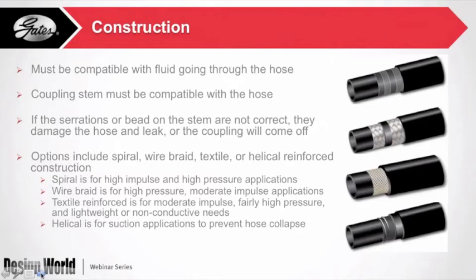Textile reinforced hoses are a little more forgiving. A lot of your textile reinforced hoses are also not the highest pressure. Some of them are going to be around 500 psi or below. So again, this opens up the opportunity for different attachment types. So we can do a push lock fitting for air, water, or multi-purpose hose, that sort of thing, where it won't need to be clamped or crimped. But always make sure that your coupling manufacturer and your hose manufacturer are the same and have signed off on your attachment method.